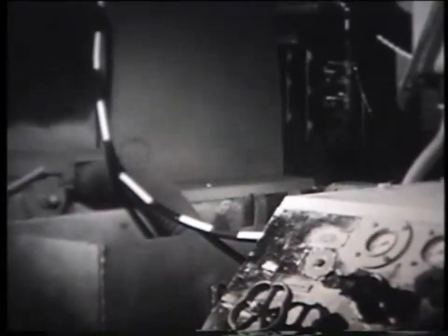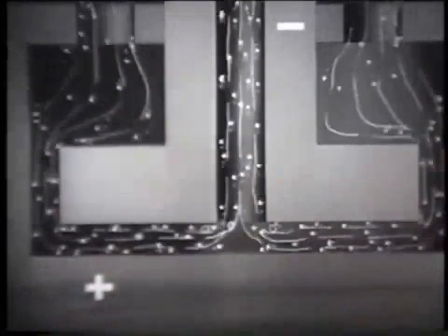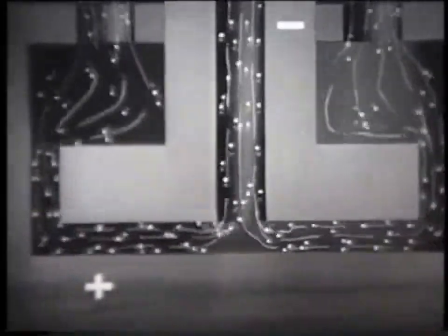To fill the gap evenly with the electrolyte solution and prevent the formation of gas cavities at the outlet of the system, local hydrodynamic resistance is created, which takes about half of the electrolyte pressure to overcome. In this case, the surface cleanliness and dimensional accuracy are maintained even when processing parts of complex shape. For the same purposes, compressed neutral gas is supplied to the gap along with the electrolyte. Here the electrical conductivity of the electrolyte decreases somewhat, but the viscosity of the liquid decreases and the gap filling improves. During processing, technologists usually experimentally choose hydrodynamic conditions that ensure complete evacuation of dissolution products from the gap.